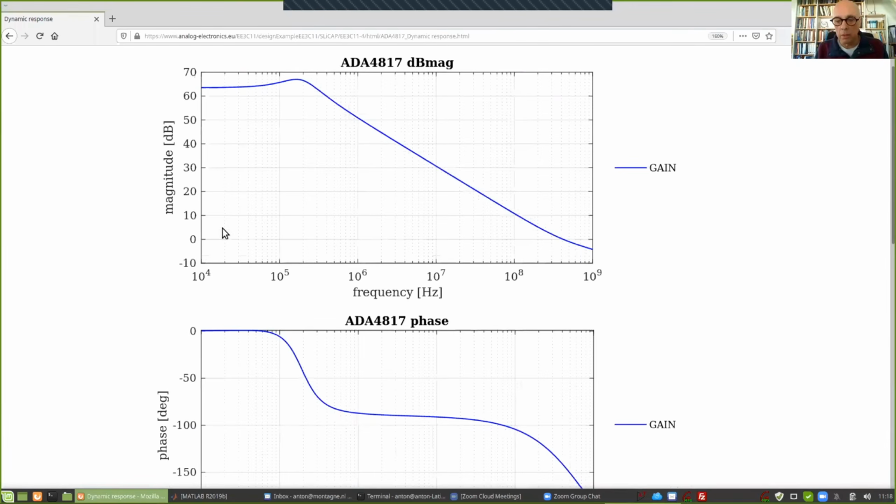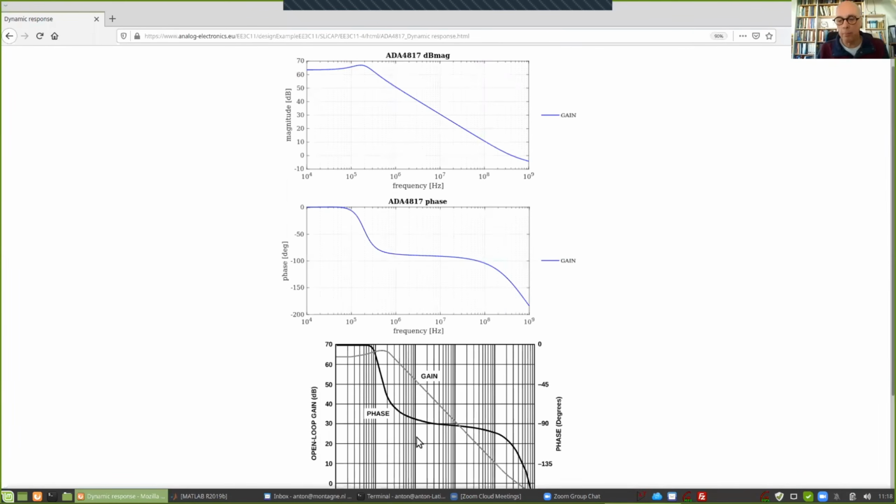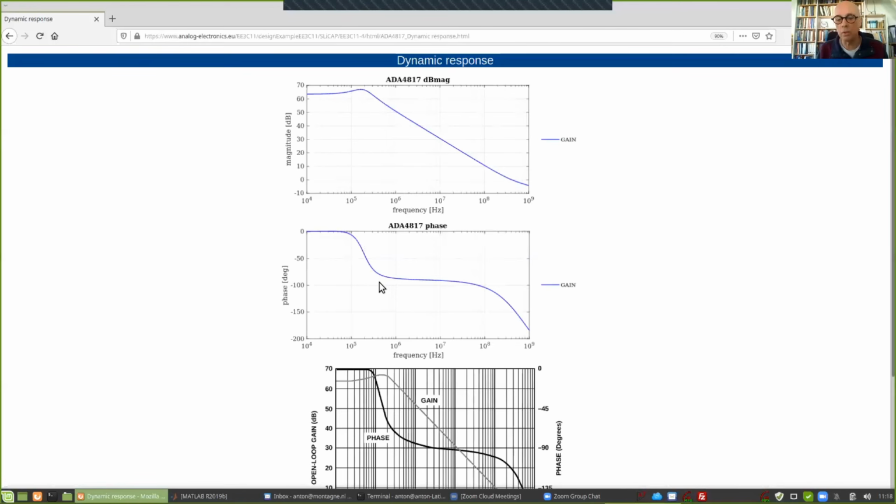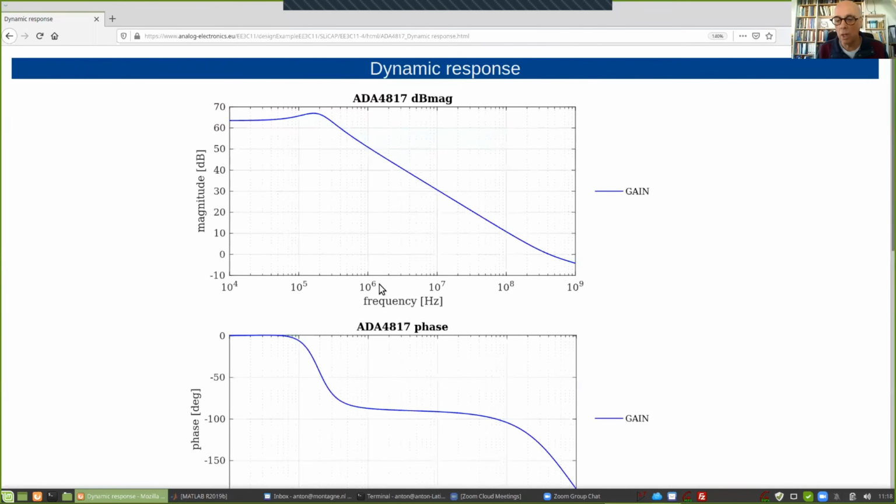Now, this is gain and phase, and this should map on this one. Well, you see, this looks quite unrealistic to me, but okay, it's what they say it is. This is also not exactly order 1 or order 2, it's something in between. But this is a nice fit. You see here also the influence of a 0. You see the phase going on like this. So this is really a very nice fit for this operational amplifier over a wide frequency range. And you see 0 dB is about 400 megahertz for this operational amplifier.